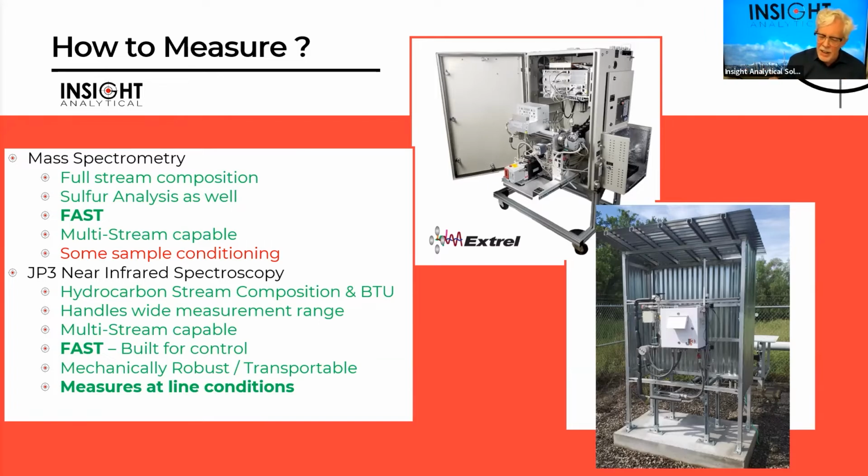The other thing is that for many of these devices, whether it's the Wobbe index analyzers or the mass spectrometers, it requires that the pressure has been let down for the gas. And that doesn't sound like a big deal. We all put regulators in. But because of effects like Joule-Thomson cooling, we can sometimes introduce compositional changes when we try to change the physical state of the fluid, lower its pressure, etc. So it can be beneficial to have a technique that's able to measure at line conditions.